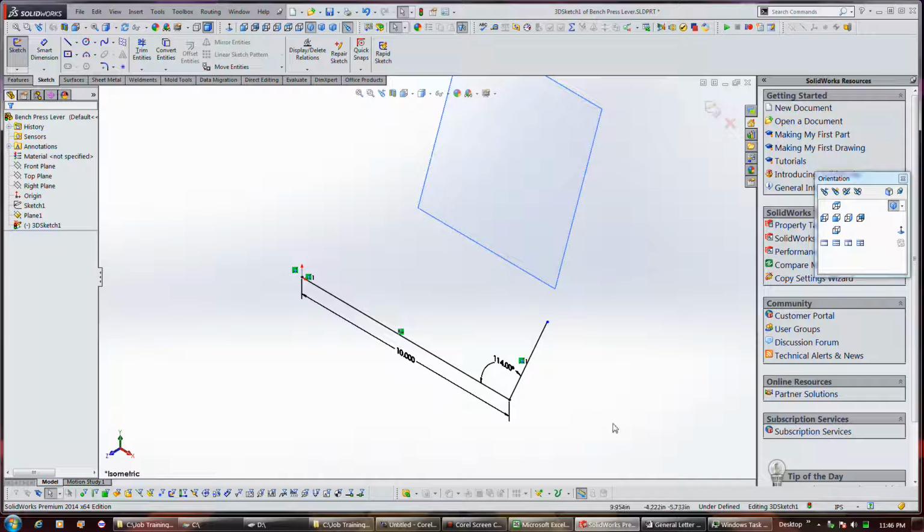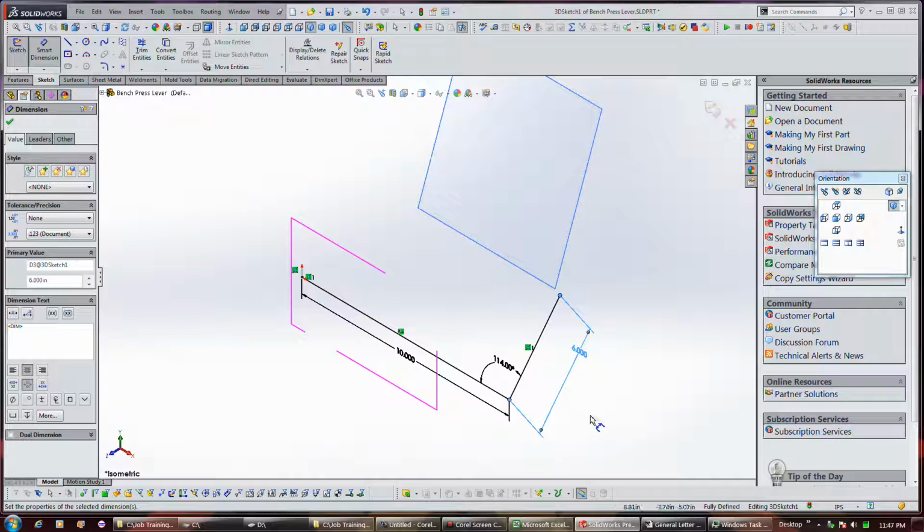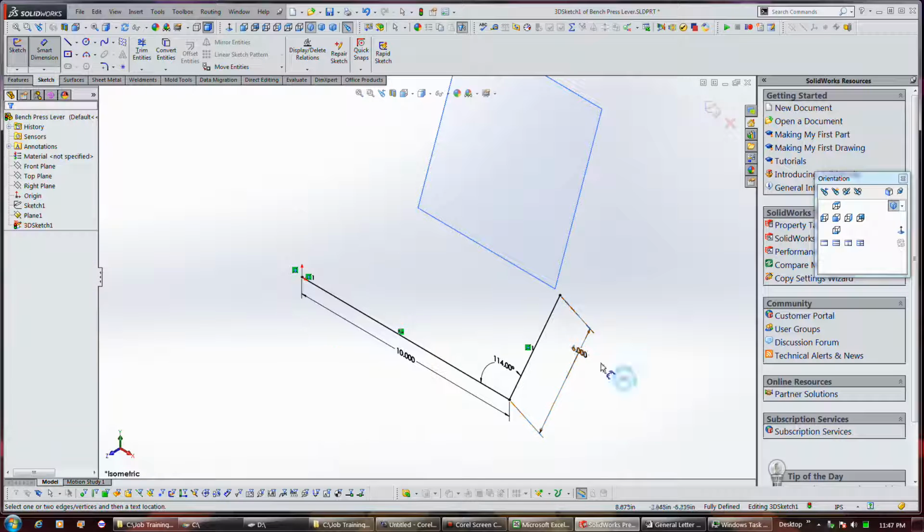Now that line is almost fully constrained, but we need to add a length to it, and he hadn't told me what that is yet. Now that I've fully defined it with the length, you can see that the sketch is fully defined at this point. But you can still see what plane our relationship is to. So he actually didn't use the shortcut that I did, but anyway.